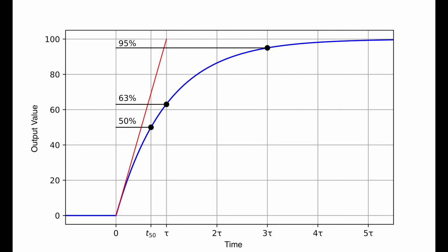Because if you make 1 minus 1 over e, so 1 minus e to the power minus 1, you get about 63%. This characterizes the evolution of the system quite well, because as multiples of the time constant occur, this magnitude tends exponentially towards its value at infinity. With the time constant, we can characterize where we are in this evolution towards infinity.